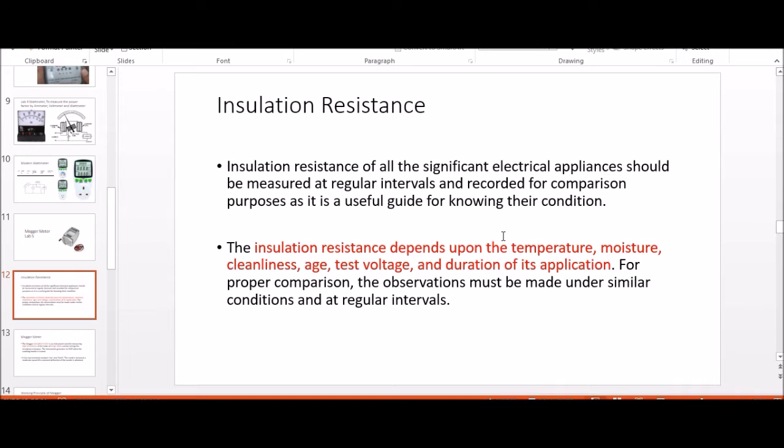Equipment can be a wire also, some electric machinery, an electric kettle, or a motor, right? All of those equipments have an external body insulation and wiring, right? And whether that body is metallic, plastic, or whatever material is used, if you touch it and you don't observe any current, then it means that it has an outer insulation and you can check that insulation with the help of a proper insulation tester.